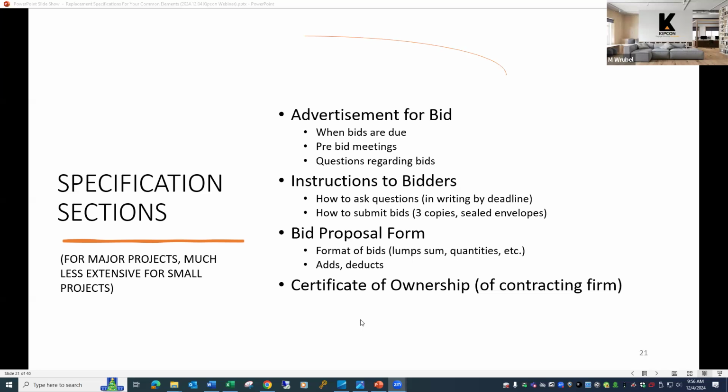And the request also includes a bid form. So the bid form is typically very detailed, and there is a section for the base bid. The base bid from the contractor includes all the work that you absolutely know needs to be done. Again, I'm going to use the example of a pavement project. During a mill and pave project for pavement, it's absolutely essential, and the project must include the milling of the surface of the pavement and the placing down of a new top course.